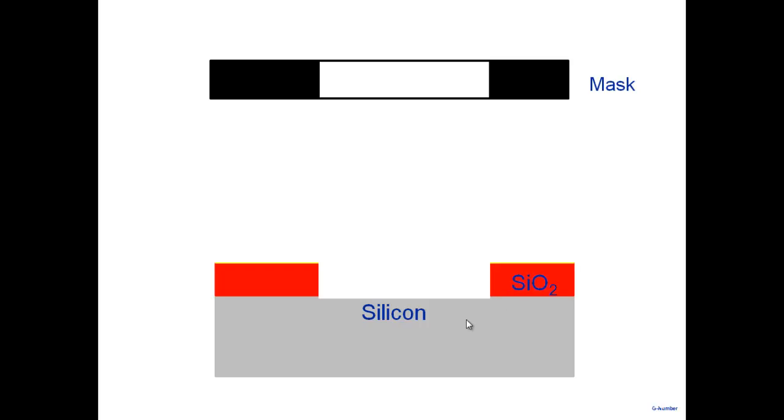But note that a series of steps are required. What is essential is that a process engineer, a person who is involved in fabricating, knows how to do silicon dioxide deposition, knows how to do N plus, knows all of those steps. But you have to tell that person in which region I want N plus. Because that N plus, later on we'll see 2 N pluses and all that, defines the transistor. So you have to tell where I want an N plus.